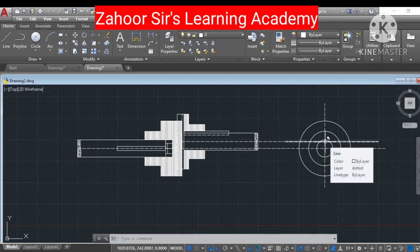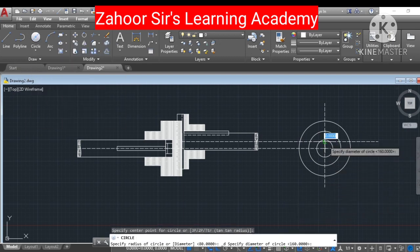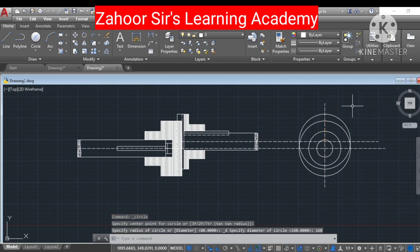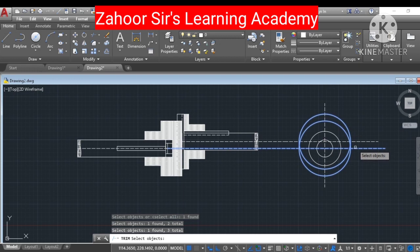The circle is 160. So I will go back to the circle command, center and dia. This is my center, identifying the center and giving the dimension, that is 160, then pressing enter. One thing is there, that this half cannot be seen, only the upper half of the circle can be seen, and the other half has to be drawn dotted. So this half is to be trimmed off. After trimming this off, I can press enter.